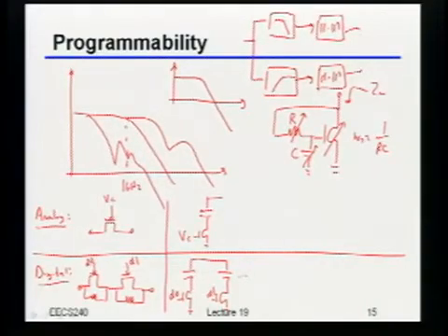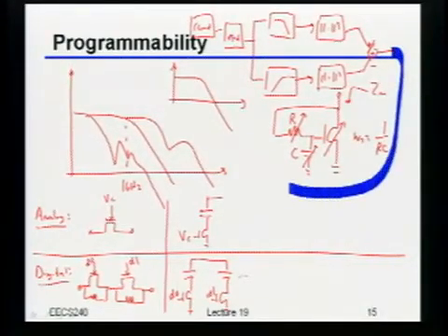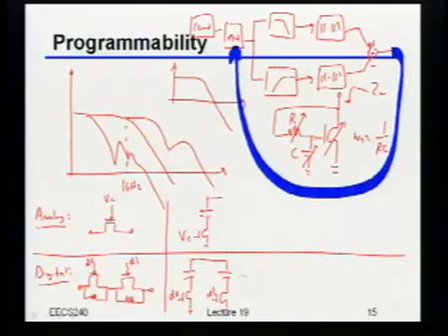Okay? If they're not the same, so that's a plus and a minus, if there's any difference there, and by the way, this is like you take your channel and then you pass it through your equalizer. So if there's any difference between what you see at low frequency and what you see at high frequency, that means you haven't tuned your equalizer to have the 0 in the right spot, right? So what you basically do is you take this and you feed it back to tune the equalizer, right?